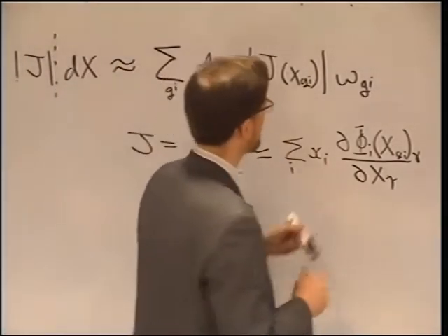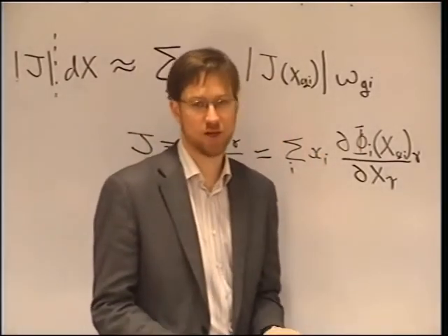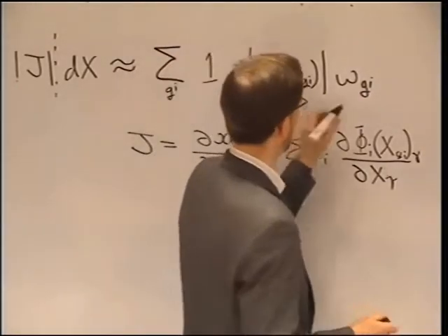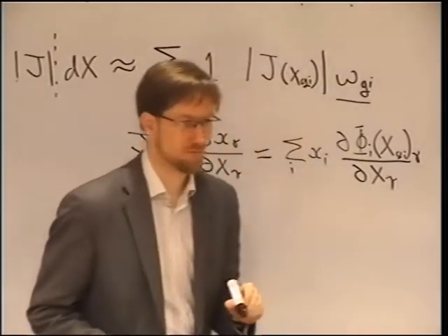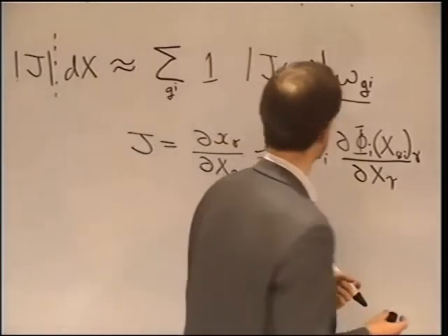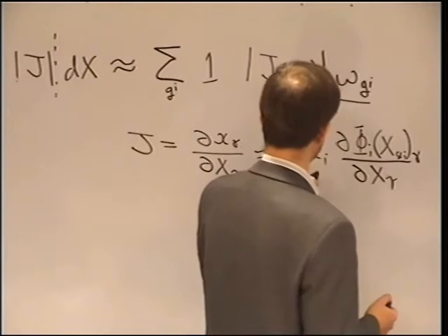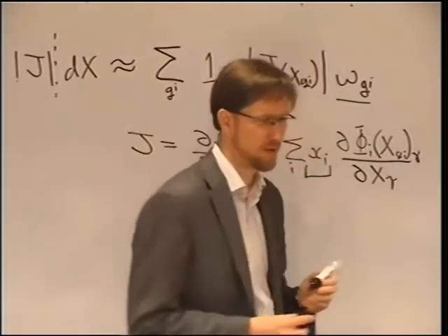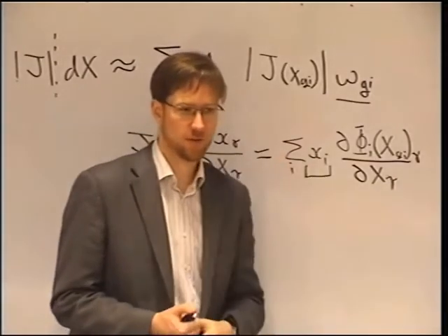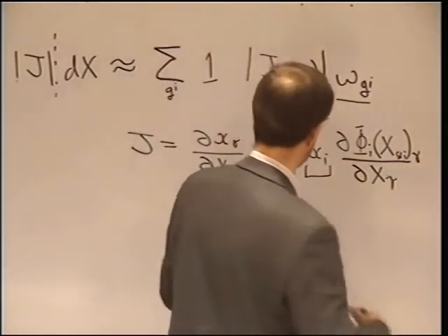Given that when we wrote down, or respectively generated using a form compiler, the quadrature rule, that's static data, so that's just sitting in the kernel, written down as a literal constant probably. It's certainly a static of some sort. And this thing is different on every element, right? This is the vector of coordinates of the nodes of the coordinate field. So this thing, that's input.